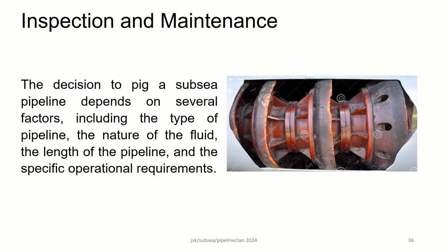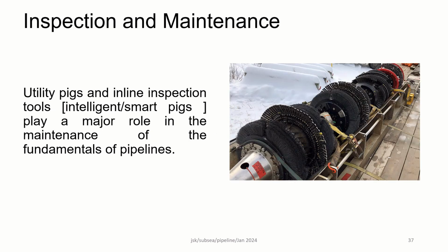Inspection and maintenance practices are as applicable as for onshore pipelines. We are also following similar practices, pigging and intelligent online pigging for the pipelines. But again, subsea pigging is a challenging job because of the infrastructural constraints.